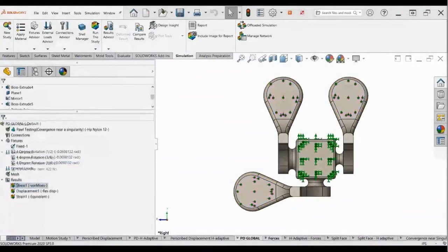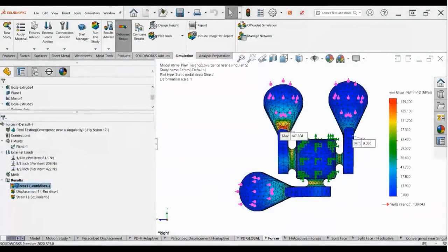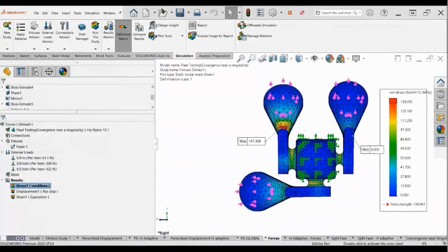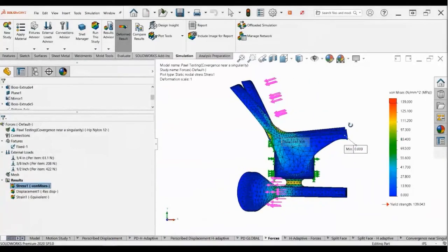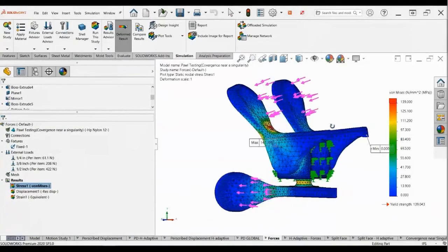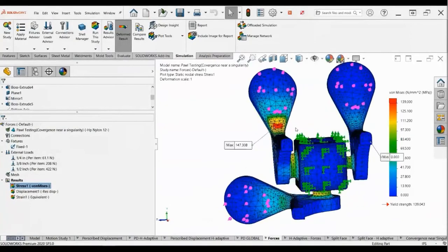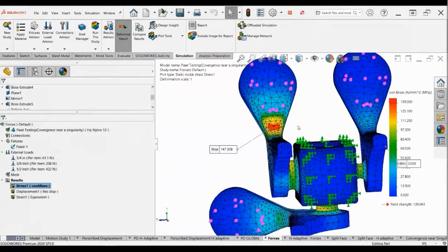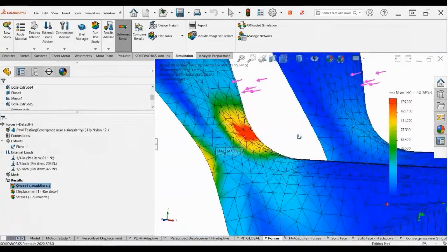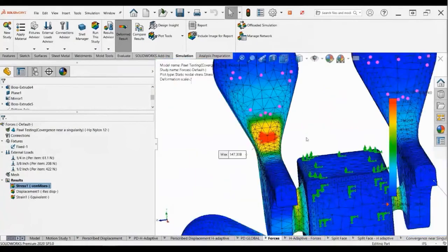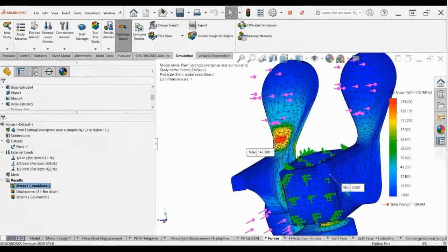In a new study, the prescribed displacement fixtures are replaced with the appropriate forces. Looking at the results, we can see drastically different deformation behavior. This is because the fixture forced the face to be rigid, but the force value allows the face to deform more realistically. The stress is now concentrating on the neck of the thumb piece more drastically, especially in the stiffer pawl that had that larger force on it.